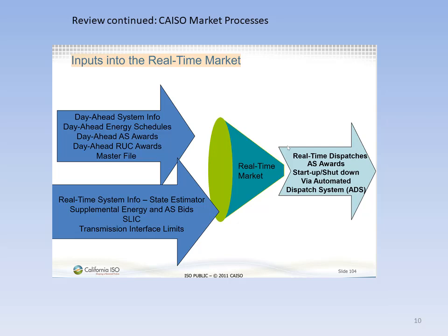Contingency reserves, spinning reserves and non-spinning reserves, are procured in the DAM to meet 100% of the contingency reserve ancillary service requirement, associated with the CAL-ISO forecast of CAL-ISO demand, to satisfy current NERC standards. If additional contingency reserves are necessary after the DAM, then they are purchased through the RTM.